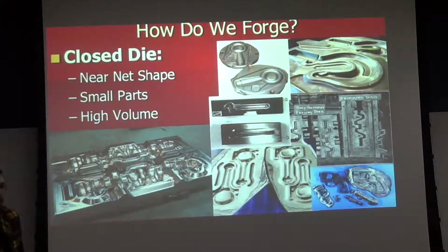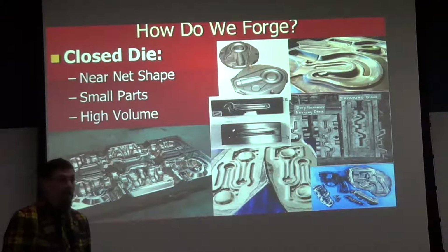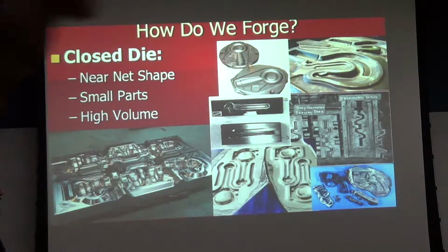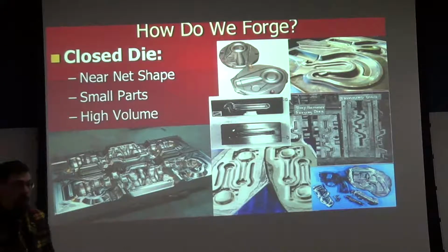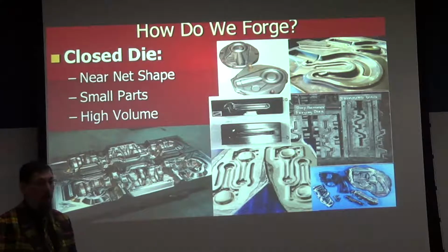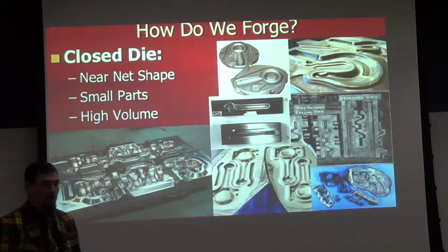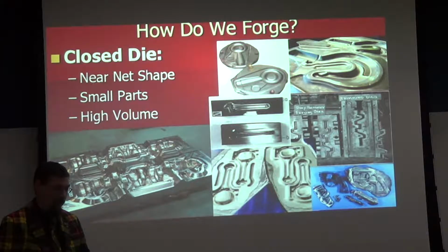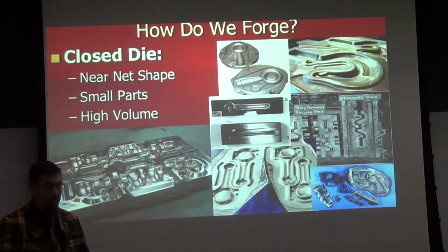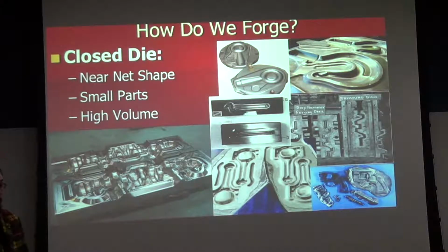Do you have sliding components in forging dies? You can. I don't have any illustrations, but if you were to go out on YouTube and look up something called a Hatebur, H-A-T-E-B-U-R, it's a closed die forging mechanism, typically done with things oriented horizontally. Those are very high-speed forging machines where they're making a lot of small parts, like say for automotive components.